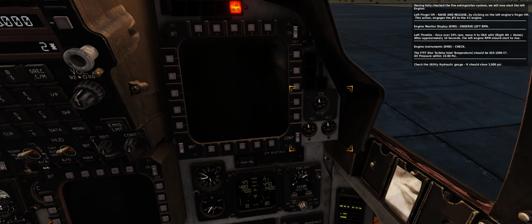When set to off, it also disables low altitude warnings, even if LAW is enabled at the same time. Override deactivates the radar altimeter, but leaves the LAW and TF warnings on. Radar power switch, set to standby.